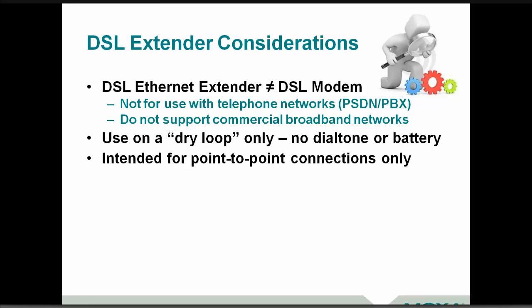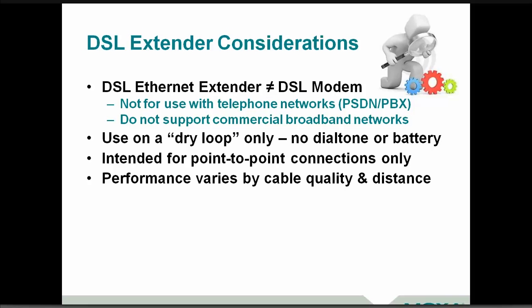It's not the same. Some of you may have had experience, and we do a lot here at Moxa with extending serial connections, such as using RS-485 technology, which has the ability to do multi-drop. But with this DSL type technology, it's point-to-point. If you need to do more than 2 connections, you'll have to insert a switch at one of those points and do a star topology to branch out from there. And of course, and I think I've mentioned this as we've been going through the tips, your performance varies by the cable quality and distance.